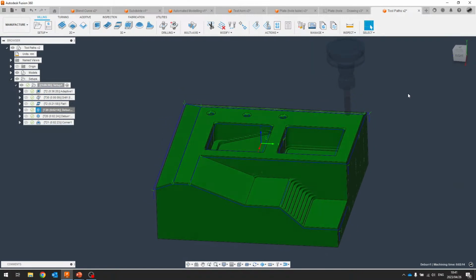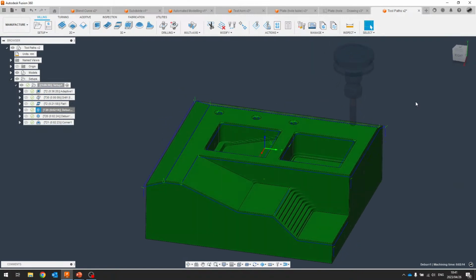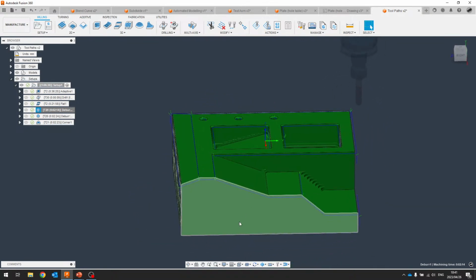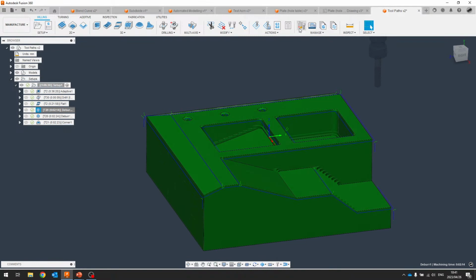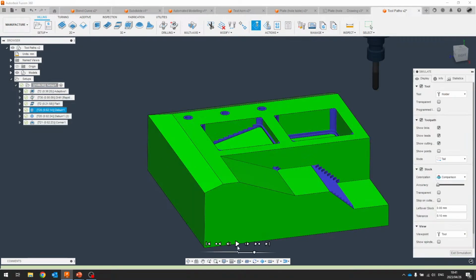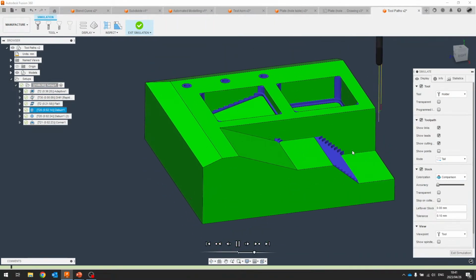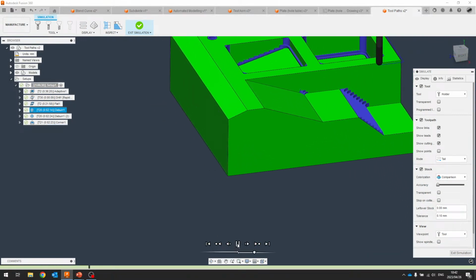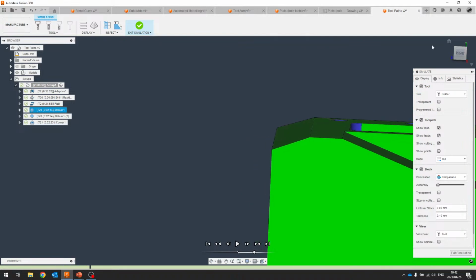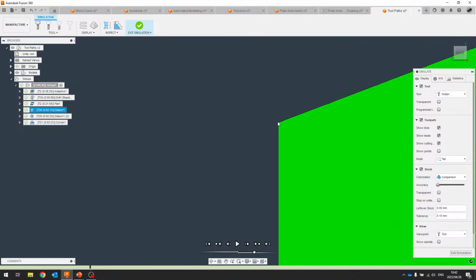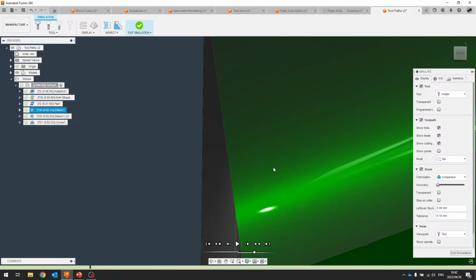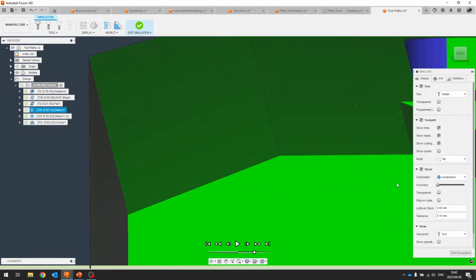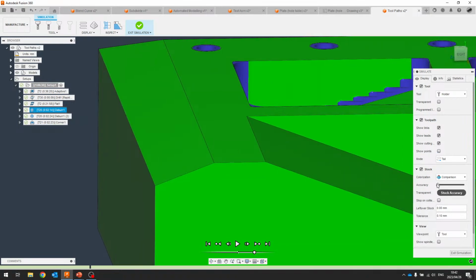So in this case here, we'll see in 3-axis, it's showing us all the corners that it can get to under that specified settings. And if we simulate this, I've got my accuracy down on the comparison, but we'll see if I just pause this, deburred this back edge, we can zoom in here and we can see, I'll probably have to boost the accuracy up, but you would see a tiny amount of material removed from there.